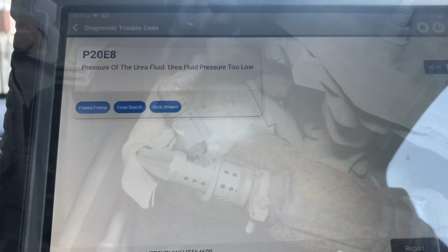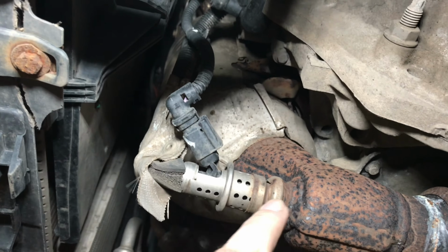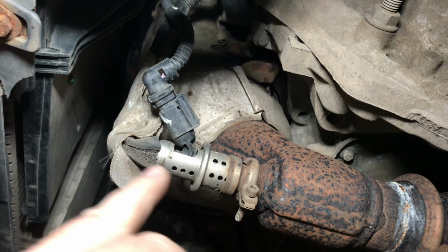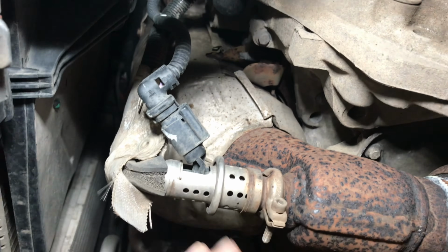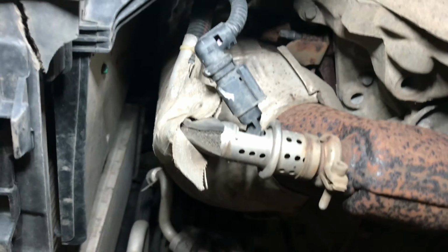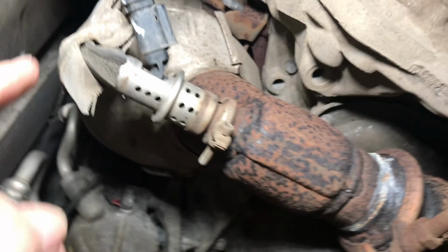Let's look at Diagnostic. Vehicle at the front, and here's the AdBlue injector. So we're going to go after that. That's the most problematic thing in these systems, simply due to the develops crystals in it. Seemingly you can wash them out, but it's only a temporary fix. This one's getting replaced.